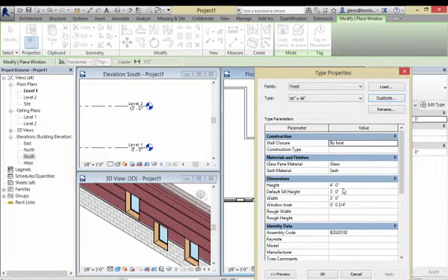And now I can go through and say, what is different about that? In this case, I'll keep it at 48 inches high, but I'm going to make it 60 inches wide. So I'll put that in there as the width. And I'll say that's either going to be 60, or I can say 5.0, whatever it is. It'll do the math for you. Say okay. Well, actually, if you're used to working in metric, you can type in US units and it'll convert to metric. You can type in metric units, it'll convert to US. It takes care of all that stuff for you.